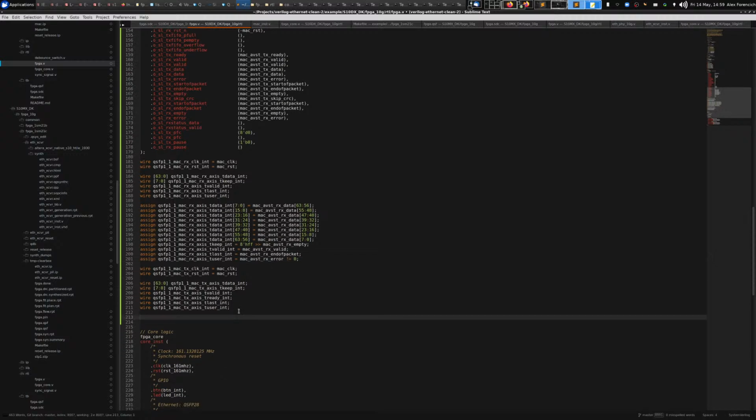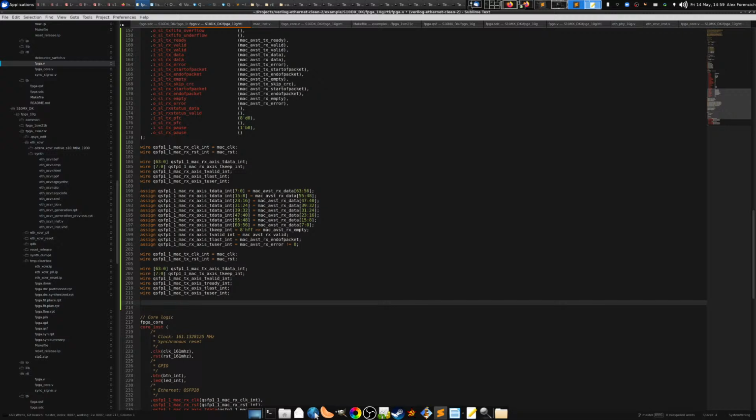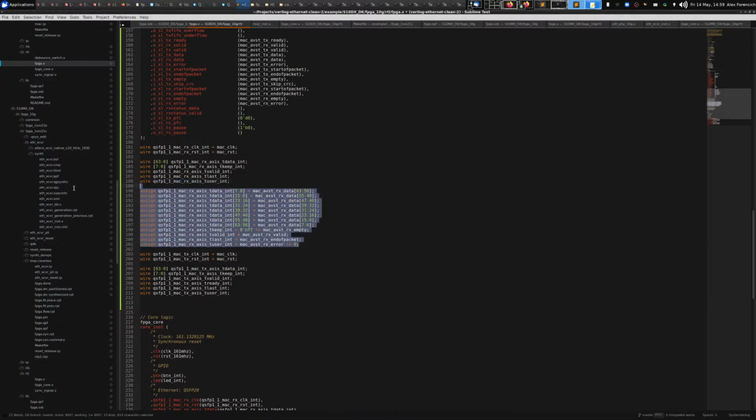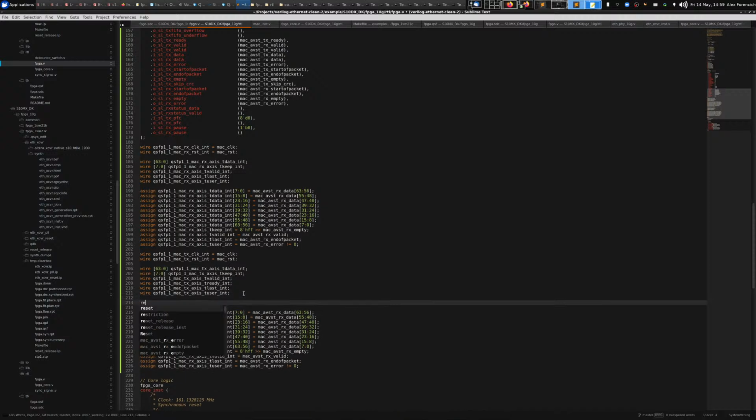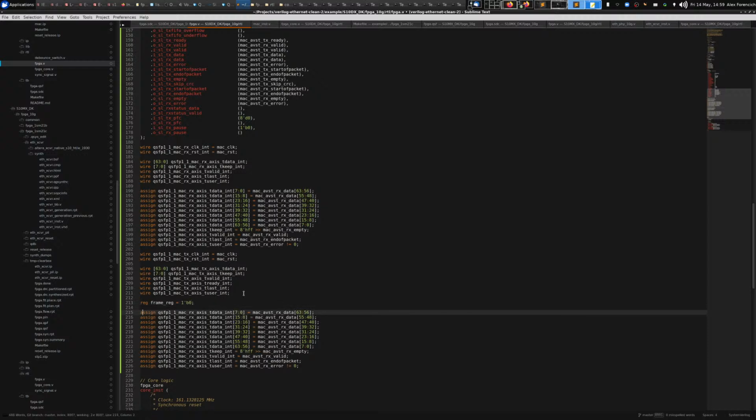Now in the transmit direction, it's similar. All right, so let's go ahead. I'm going to copy all of this and then reverse it, and I need to do a little bit of additional work here. The one thing is I need a register here. Okay, this is going to be frame reg. This reg is set when you're in the middle of a frame somewhere, and we need that to properly regenerate the start of frame signal.